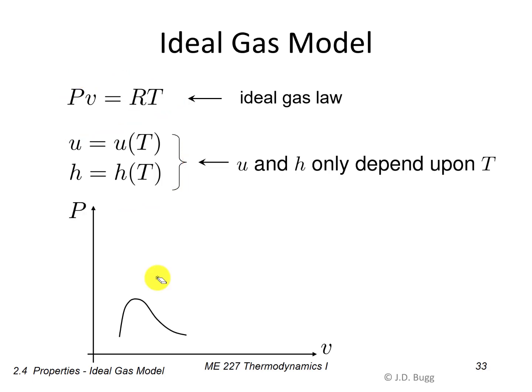Now, so far I've talked about ideal gases and substances that are changing phase as if they're two different things, but of course they're not. Really, the only thing that's different is the range of conditions that we're working with. So here is our PV diagram again. Here's our saturated liquid and saturated vapor lines, critical point at the top. We've talked lots about this diagram so far.